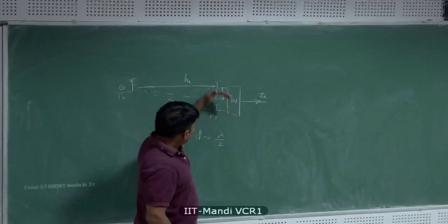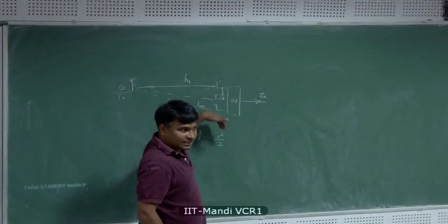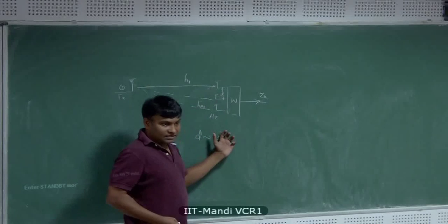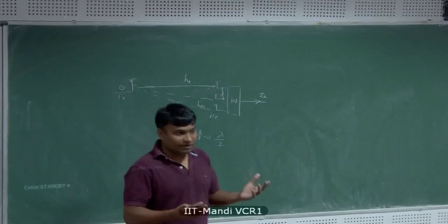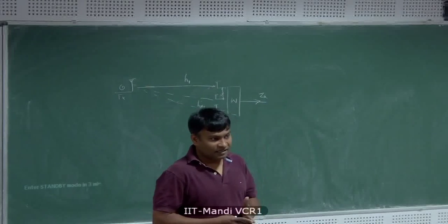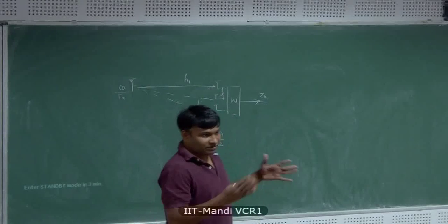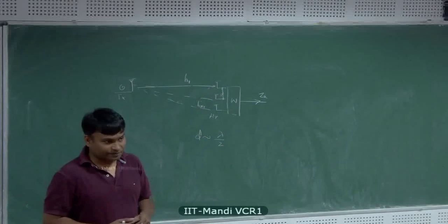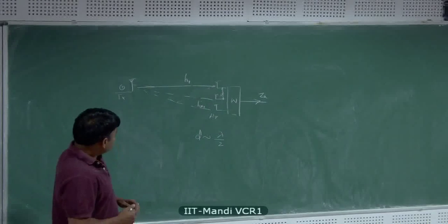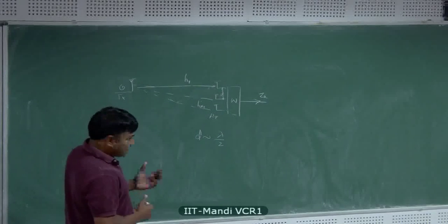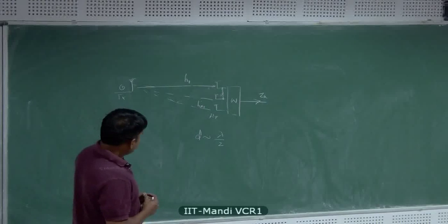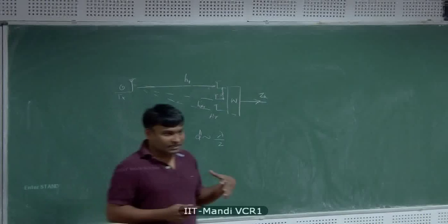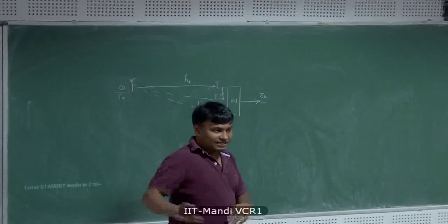By combining, you not only coherently capture the energy contained in all NR channel paths, you also get diversity combining, which is of order NR, because you will get the sum of squares of channel gains benefit. We'll show that. In this lecture, we're not going to specifically focus on this diversity combining gain. That will come about as a side product.